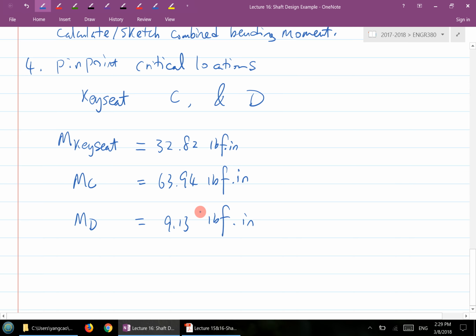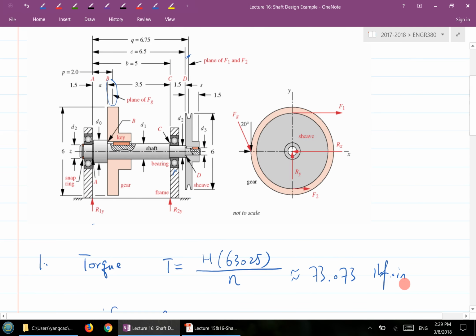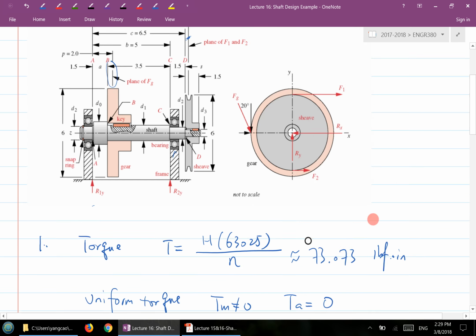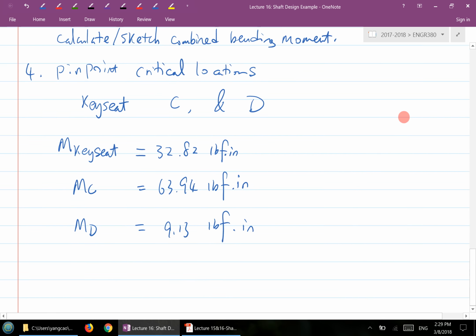And the other thing is, because this is fatigue loading, the shaft is rotating. The force is constant here, the force is constant here, right? So in other words, for the shaft, what you're looking at is that MA is not 0, and MM will be 0. That's what we call a completely reversed loading condition, right? Completely reversed. And the values listed here are the amplitude values.